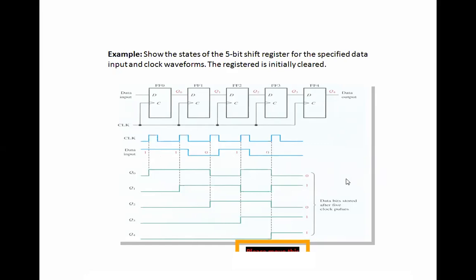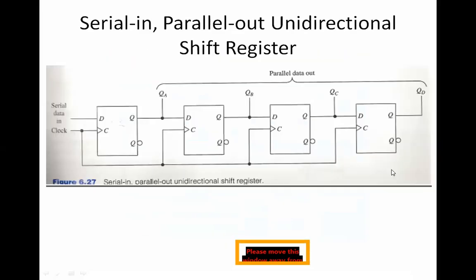Thank you, students. So now we'll go to the next one, which is serial in, parallel out. This is also a unidirectional, one-way shift register. So I have my D flip-flop here, same thing: 4 D flip-flops, with clocks connected to each flip-flop. The only difference is that instead of taking the data at the end, I am taking the data intermediately.